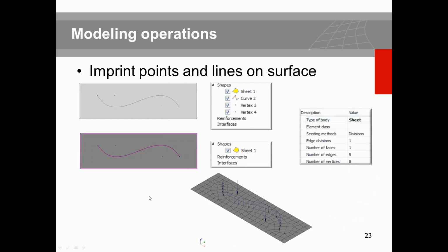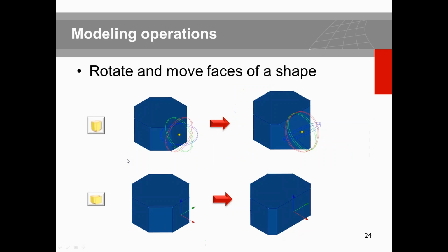And one of the most important things, again, I emphasize that, is the definition of the load and boundary condition. These things in DIANA 10 are defined at the geometry level. So if I have a geometry, I can define a reference curve. Then I imprint the position of this curve, which later we're going to impose some sort of edge load or point load. I imprint them on my reference surface and proceed to the next level, which is loading. So before loading, before defining boundary condition, you should make sure that the bases basically do have imprint on the main body.